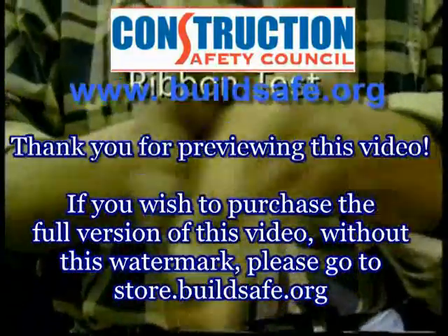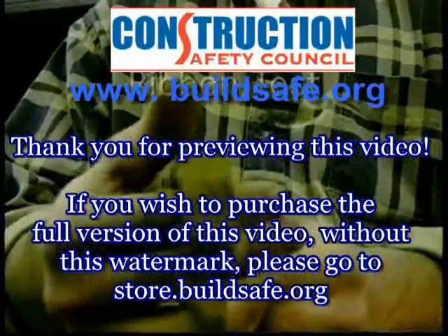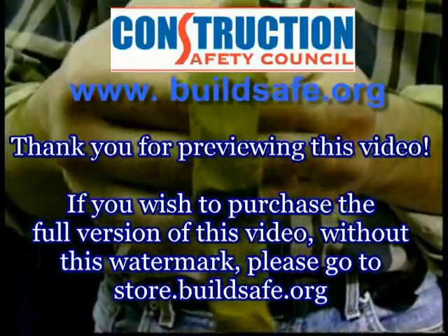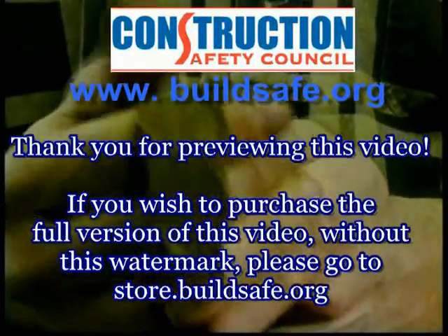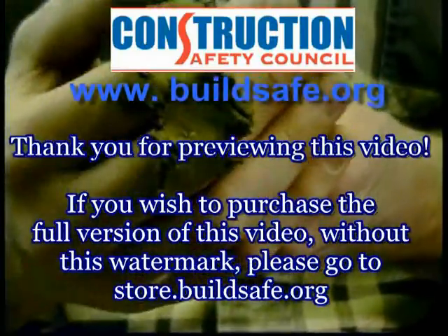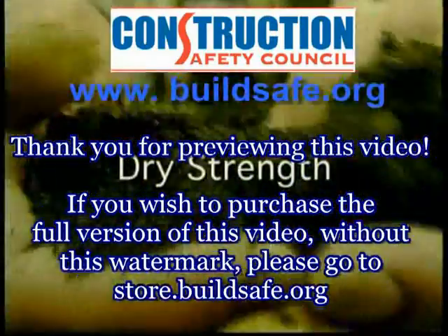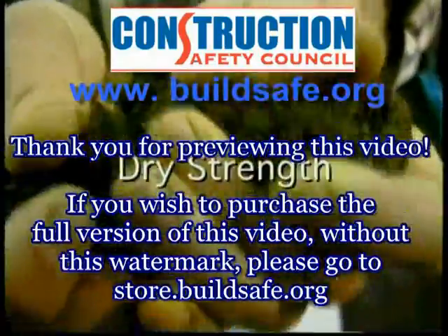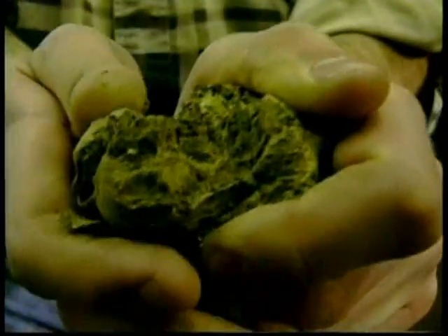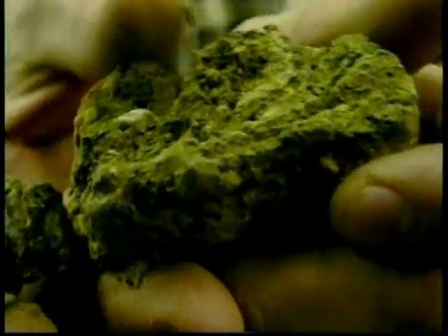In the ribbon test, the ball is rolled into a cigar shape, then pinched into a ribbon. The longer the ribbon, the more cohesive the soil. If the ribbon breaks off in chunks, that indicates the presence of granular material. The dry strength test is used to determine the approximate strength of a soil sample. How difficult a clump of dry soil is to break up or crush is related to its cohesiveness. The harder it is to break it or crush it, the more cohesive the soil is.